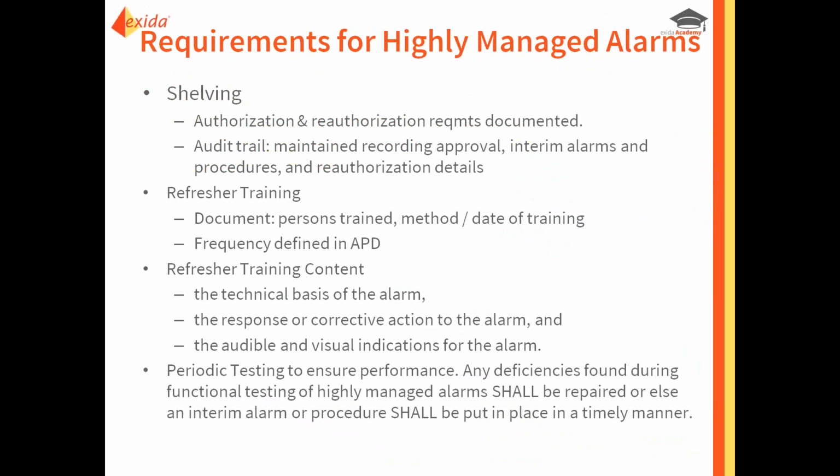Now, where did this all come from, or why is it there? Well, the genesis of the concept of highly managed alarms comes from the OSHA PSM regulation. If you thought about having an alarm that was falling under OSHA PSM, and you thought about the requirements that are called out there and what you would need to do to comply with OSHA PSM, that is basically what these requirements represent in the standard.